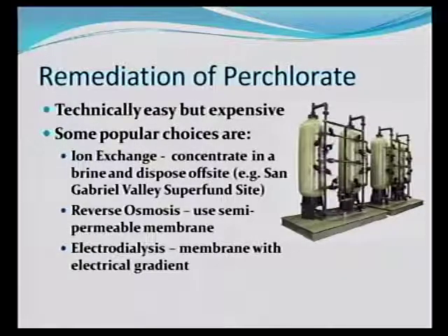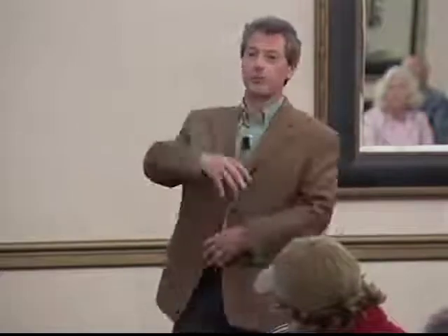You have to do what's known as recharging the resin. So you've got to find something so the perchlorate gets stuck to the resin, then you put something through that knocks it back off. It's hard to find something that knocks it back off. So it's kind of expensive, but it's really only a problem when you're treating tremendous amounts of water. So you have entire aquifers that are contaminated, and this is a drinking water aquifer. This is a huge problem in the United States because it's difficult to treat those volumes of water. For focused contaminated sites, compared to other technological problems, it's not quite that difficult.